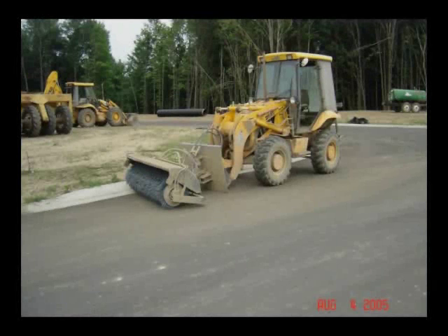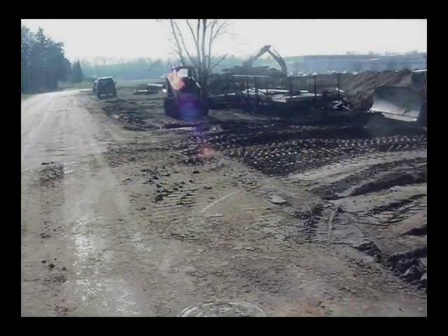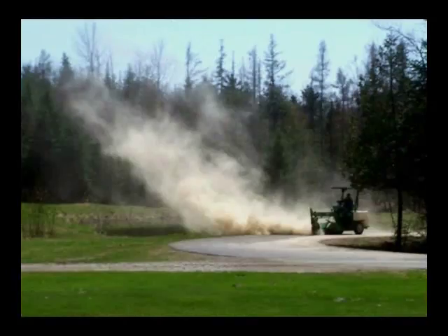Periodic street sweeping in the vicinity of the exit roads may be necessary even with the use of rock construction exits. Sediment that collects on the shoulder of the roads or the curb systems from the sweeping activities must be removed. If a large amount of sediment must be removed, or if sweeping the sediments is likely to create excessive dust, use another means of removal or dampen the sediments prior to sweeping.